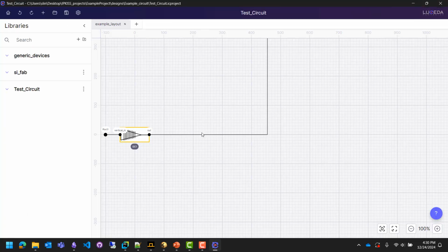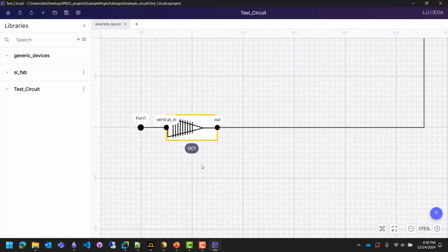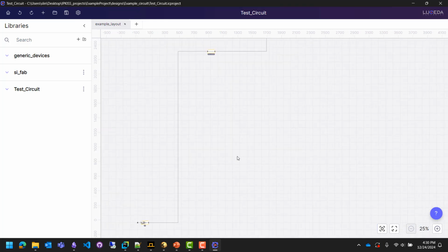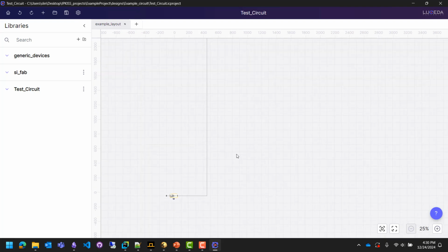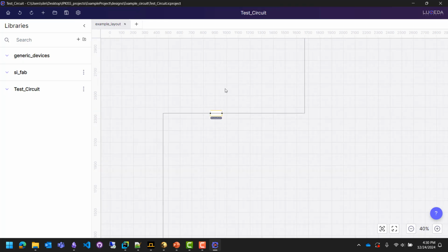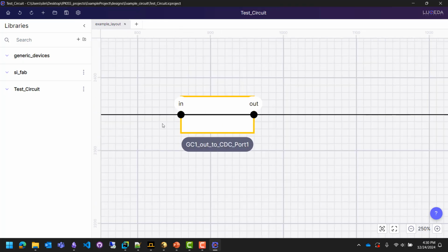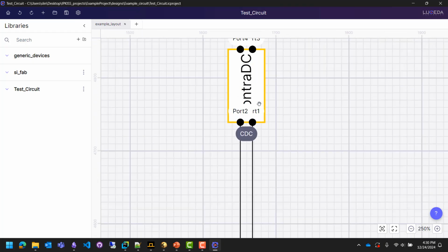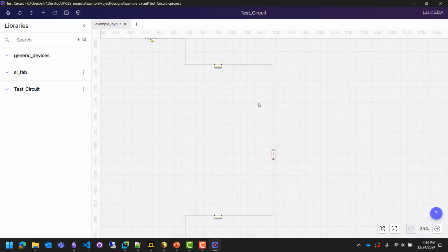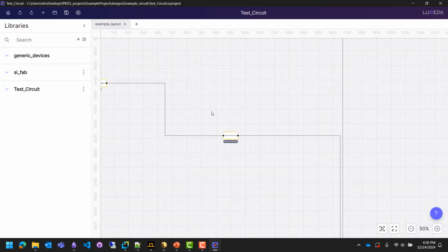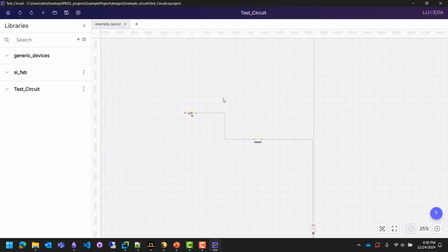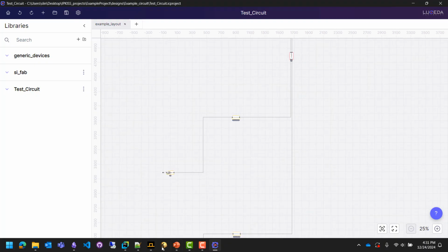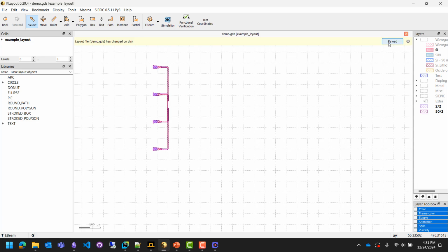So here I launched IPKISS Canvas, and right off the bat you can see our grating coupler. We'll have to zoom out quite a bit, and the reasoning is because we used our own units. So you can fix this by using different units. But here we can see that IPKISS Canvas also conveniently added for us a waveguide object as it moves on to connect to our contradirectional coupler object here. And then just like our layout, it then goes back out to our other grating coupler ports. So a quick and easy way to go directly from a script into a circuit model, or if you want, it can also go into your GDS layout.